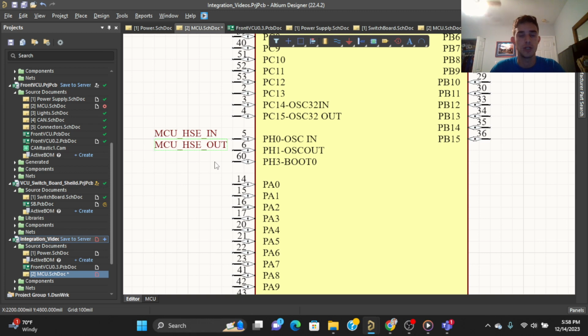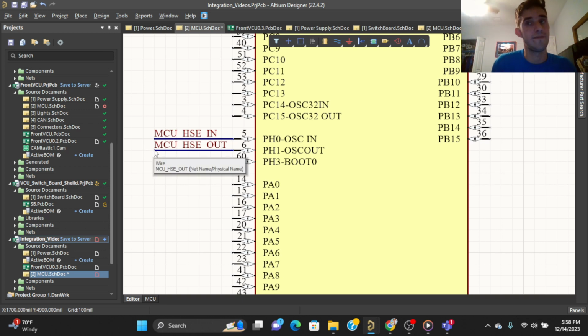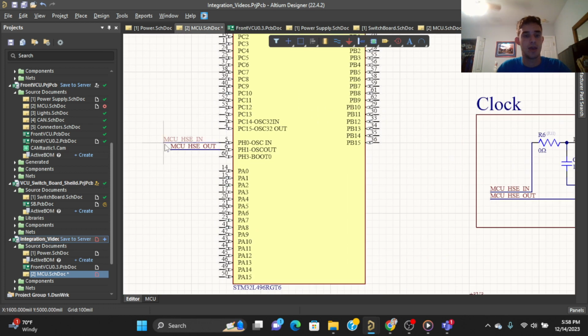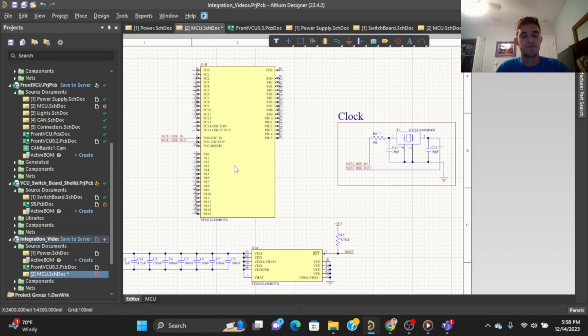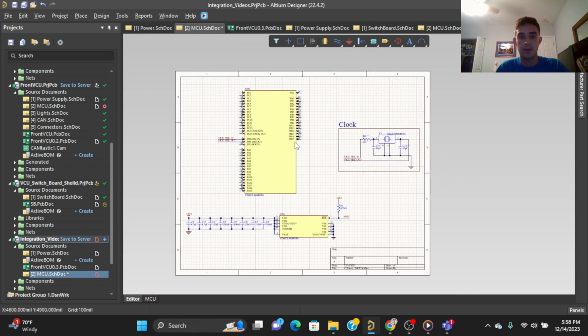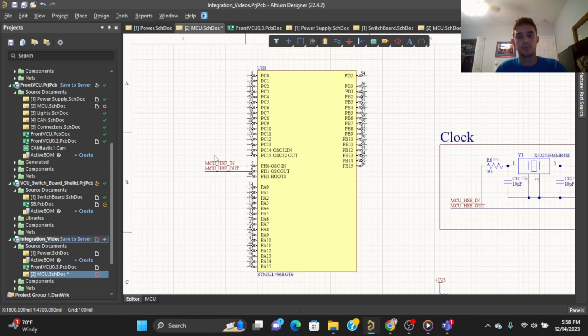That's for a 32.768 kilohertz oscillator. And you might think that's a random value, but it is half of around 64,000, which is, I believe, the maximum value of a 16-bit number. So it makes sense when you're looking at it in binary, if you're looking at the binary value, as opposed to the decimal value. Okay, so we have our clock and our microcontroller set up.